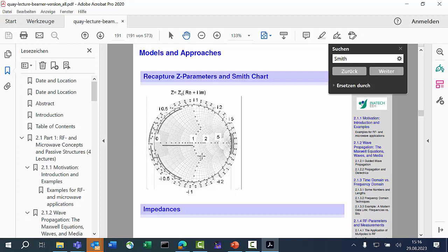For example, if we are looking at an impedance of 1 ohm in a 100 ohm system, then you simply don't see anything, because if 100 ohms is my reference, then 1 ohm is somewhere here, and I don't see anything. Now I want to distinguish between half an ohm and 1 ohm, and on the page it's the same.